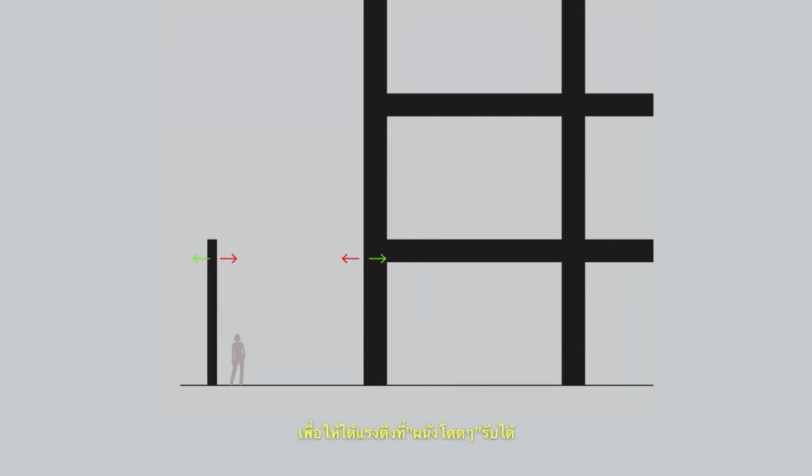In worst case of practice, we might think about reducing the pretension force to be in the range that the main structure can achieve. Then what we're gonna have is incomplete cable net system, and of course we will see some member sags.